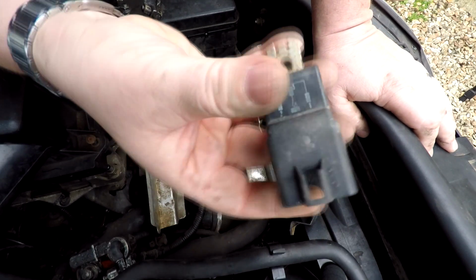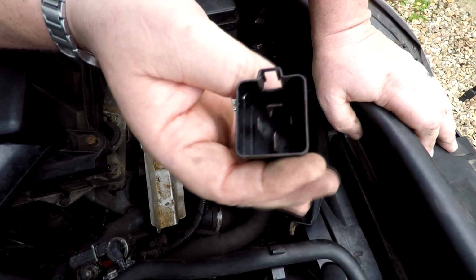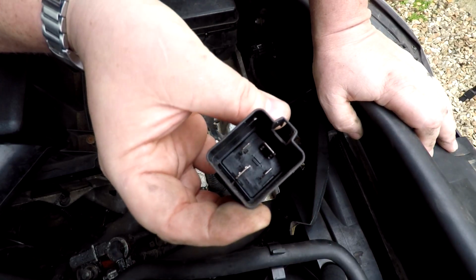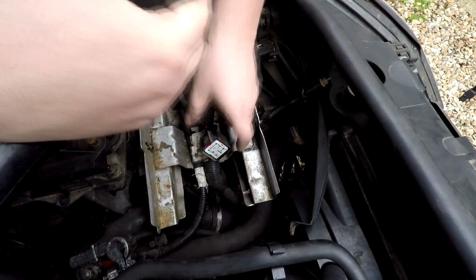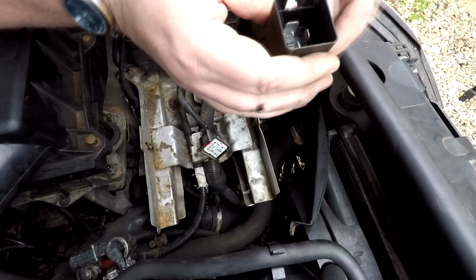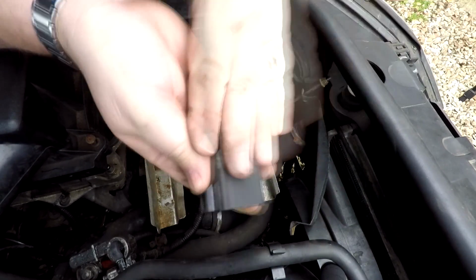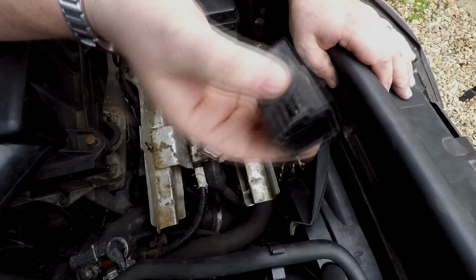So the only way to do that is to actually open it up or replace this unit. I don't really want to do that yet. I'm basically confirming on the outside of the relay that it looks clean and that the connector looks clean with no signs of any arcing at all. So I'm happy with that, and I'm happy with these terminals, but I'm not necessarily happy with the internals yet. There's some more investigation to do there.